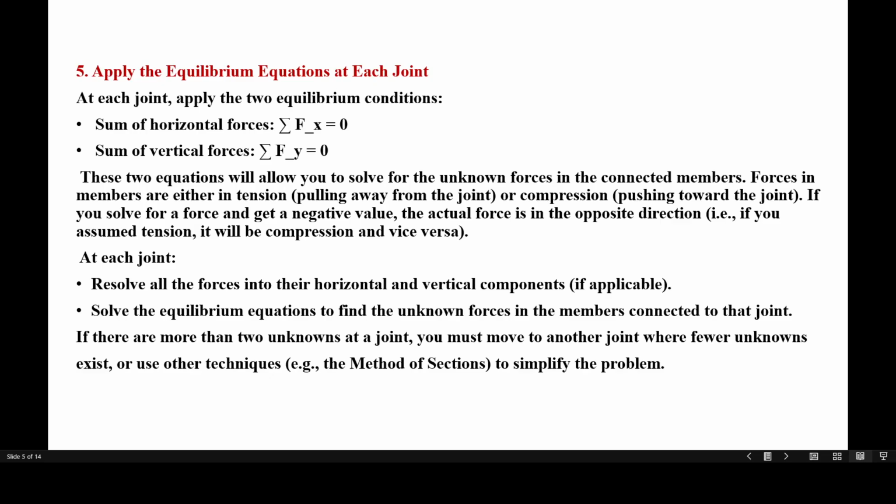If we get a positive value, it means the member is in tension and is pulling away from the joint. If the value is negative, then the member is in compression and is pushing towards the joint. You can take this member as your reference.